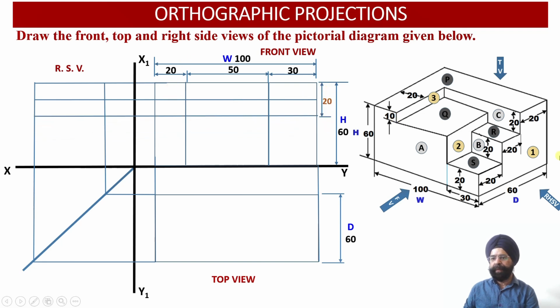So this is 20 millimeter corresponding to this surface, B, C and A surface over here. So this is 20, again you have 20 and again you have 20. So on the right hand side I have 3 steps, 20, 20 and 20. And please check, I have already marked this height of the solid is equal to 60 millimeter. And I have also marked these 3 dimensions at 20. So this dimension becomes a redundant dimension. It has been drawn only for the purpose of understanding.